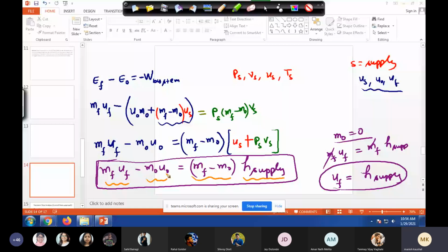For example, I will prefer the control volume approach, because there is a very thin line of confusion about which pressure we should take for work done while taking the control mass approach. There is always a confusion that if the gas is entering, the outside pressure is higher than the inside pressure of the tank. So why don't we take this pressure difference?